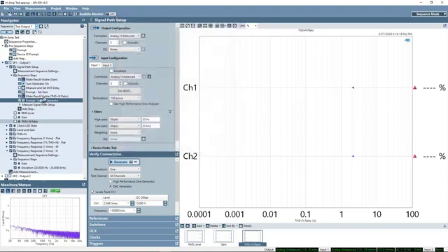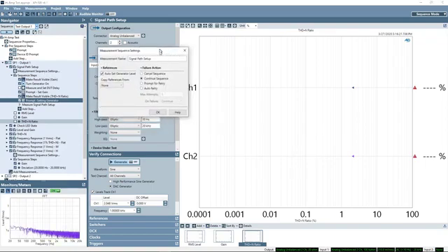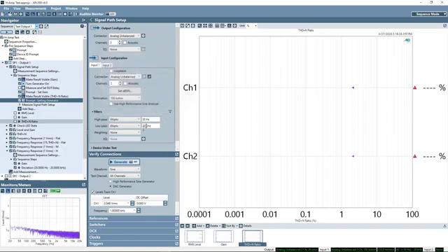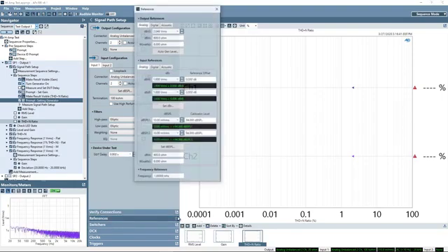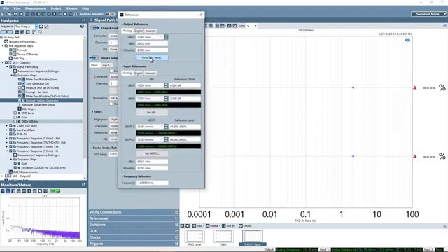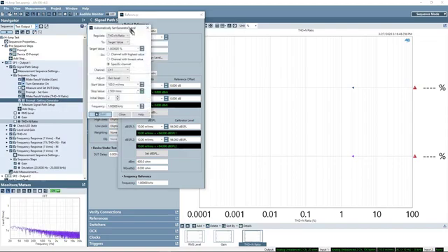It's not through a sequence step in this case, it's through the measurement sequence settings. So if we click on this node, we can see that for signal path setup, we have this checkbox, auto set generator level, and it's been checked. And this will cause the system to regulate and run the auto set generator level feature. That feature is available in the References tab down here under auto gen level. So it's been pre-configured in the project to regulate THD plus N ratio to a target value of 1% on a specific channel, being channel 1.